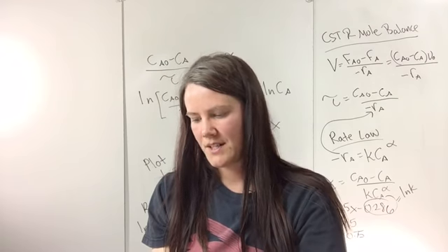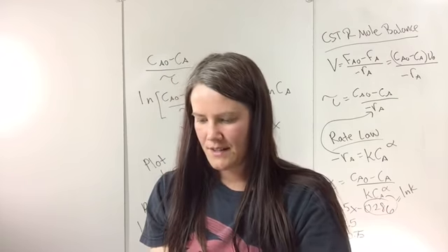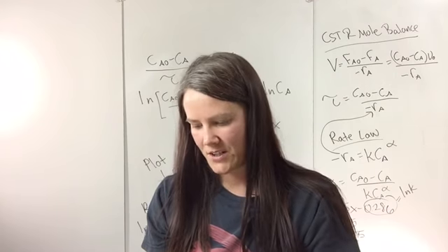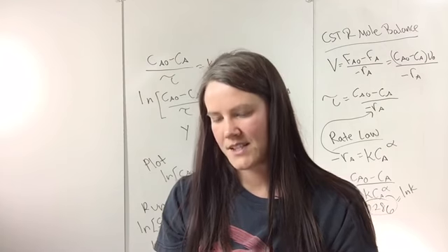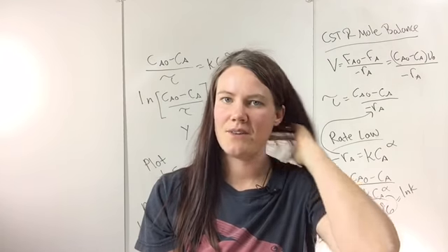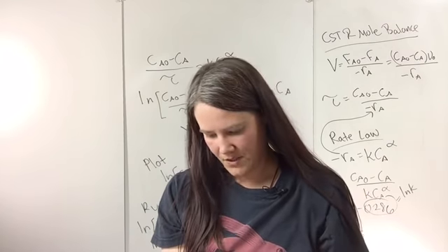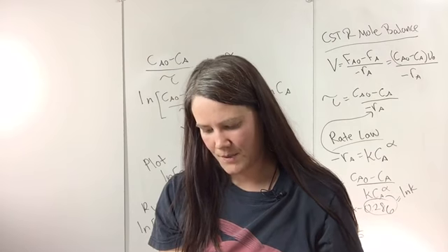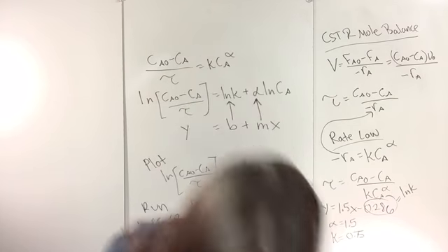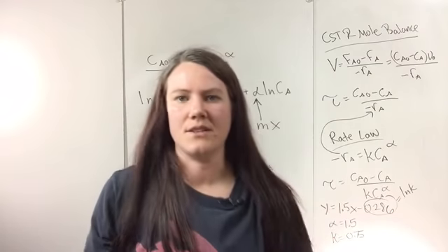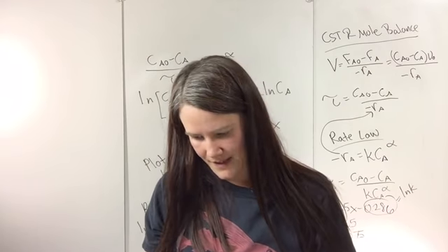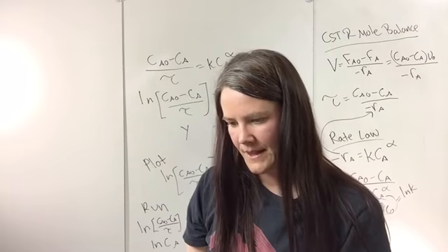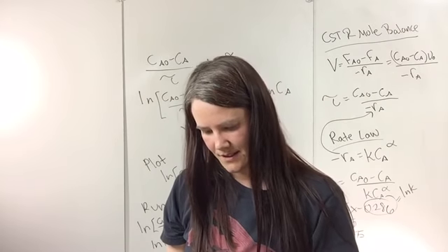So it goes through there, you have your reactions, so you number each reaction. You have the mole balance and your net rate laws. Definitely make sure you know how to write net rate laws. Stoichiometry, pressure drop, and then combining. And likely for these problems, you'll need an ODE solver. And so I had an example problem on this.